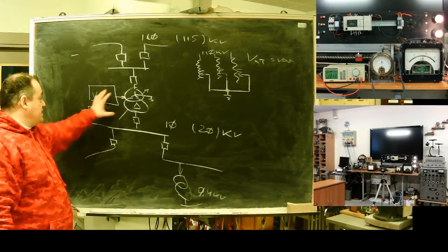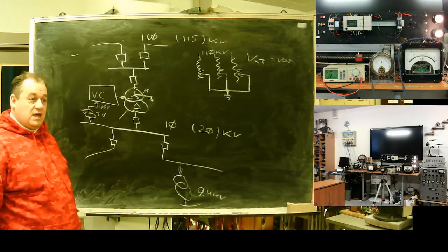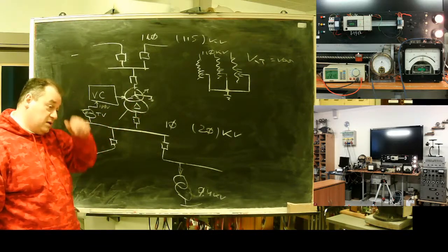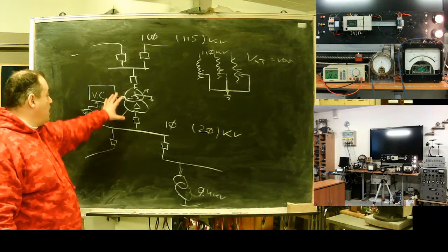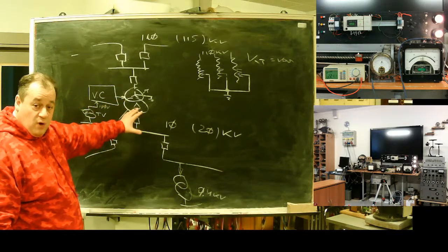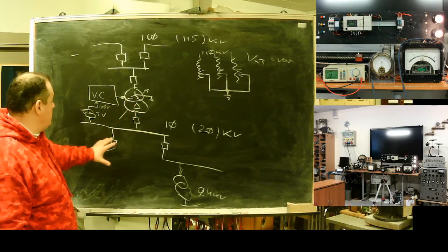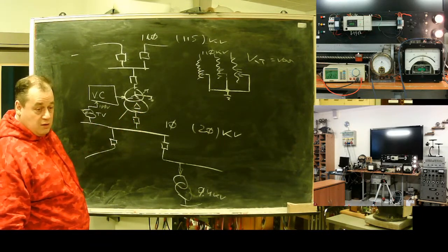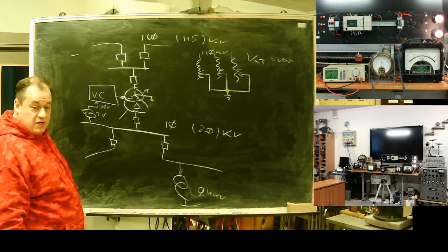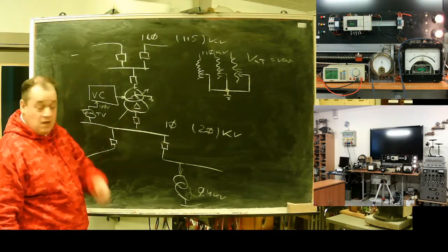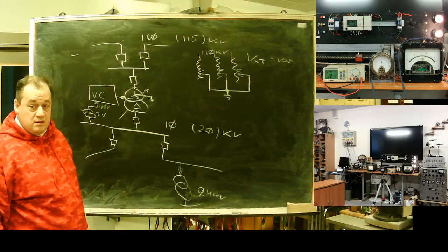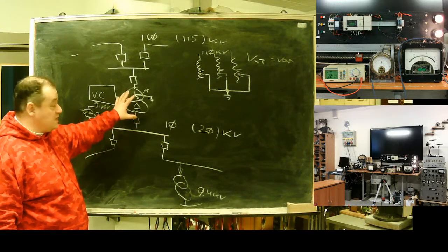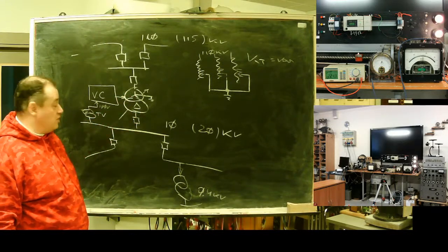The voltage controller sends a tap change signal to the transformer's tap drive to adapt the transformer's ratio so that the voltage at the bus remains constant. You can see my demo is somewhat close to this voltage control installation.